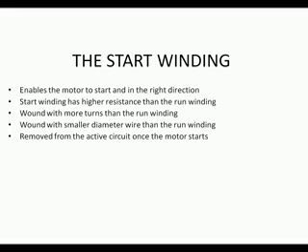As the number of poles increases, the motor speed decreases. The motor speed is the frequency times 120 divided by the number of poles. In the United States, the frequency is 60. For example, a two-pole motor will turn at a speed of 60 times 120 divided by 2. So 60 times 120 is 7,200, divided by 2 equals 3,600. The motor will actually turn at a speed that is lower than the calculated value. The term slip is the difference between the calculated and the actual motor speeds.